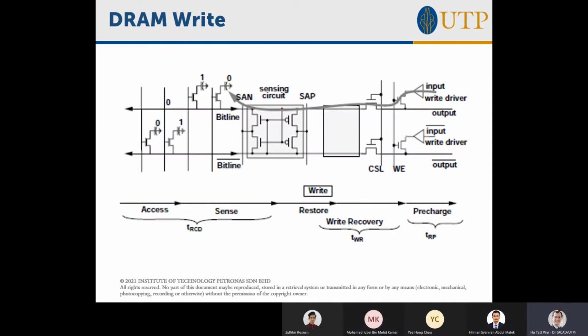I'll share this. So as you can see, it's a digital circuit, but there are a lot of analog components in it. And the whole point is because they want to save power and they want to speed this up, right? And they also can save on size because if the capacitance is small, each bit can be held very small, right? If I make this capacitance small, one bit is going to be really, really small. Then I can charge it faster, use less power and all that.